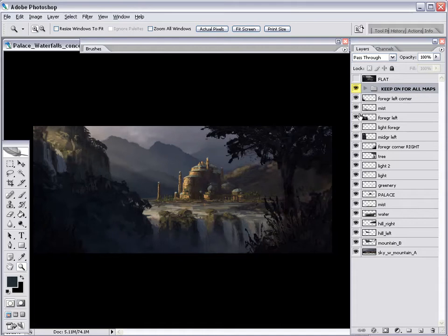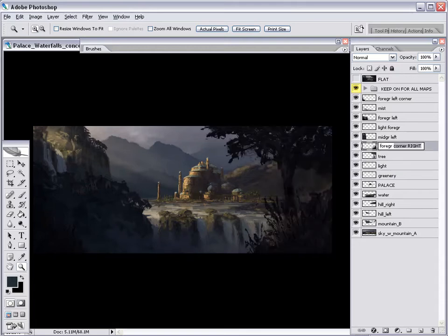Certainly at this point in time, you want these elements named. It's important to name them, just because you have to manage all of these elements as they come from Photoshop. They become texture maps. They're going to have their alpha channels that show 3D Studio Max how you want them cut out, and then they have to be brought into 3D Studio Max as a texture map.